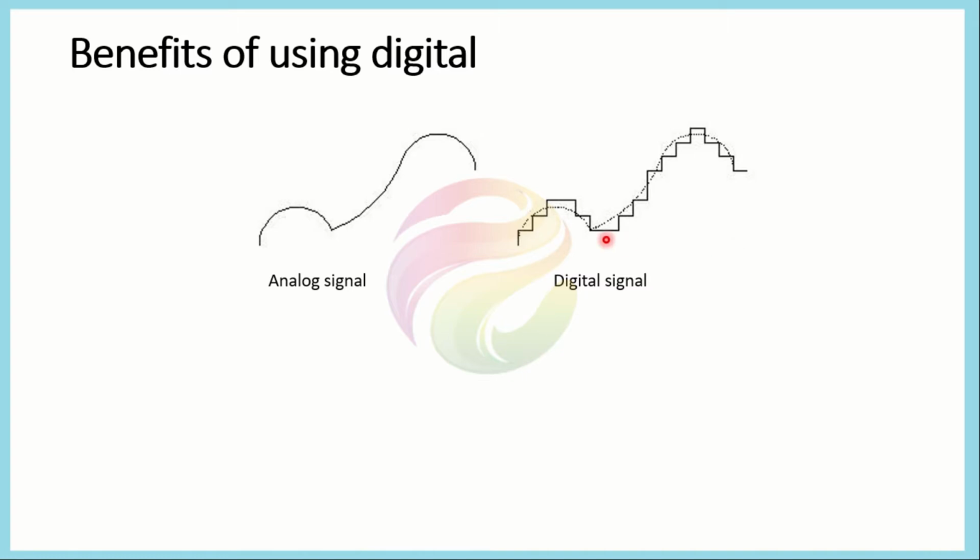So when we plot them, we use a specific type of circuit or terminology, which is known as the zero order hold. What it does is keep the value of the system constant until we get the new value. So the value at time 0 will remain constant till time 1. The value at time 1 will remain constant till time 2. Whatever the value at time 2, it will remain constant till time 3. So we assume that in between the instances the value remains constant.